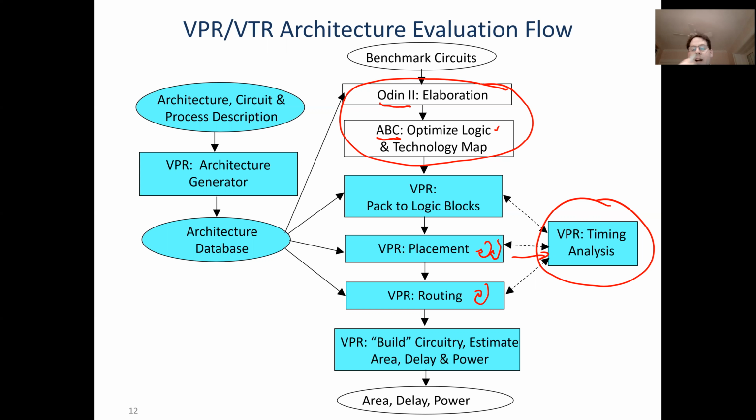There have been various efforts to try to make synthesis more timing driven. You can get small gains, but not that much. And it's basically too hard to predict. You're so early in the flow that just trying to minimize the depth of everything, trying not to have too many lookup tables in series, is a pretty good heuristic and probably better than really detailed predictions.